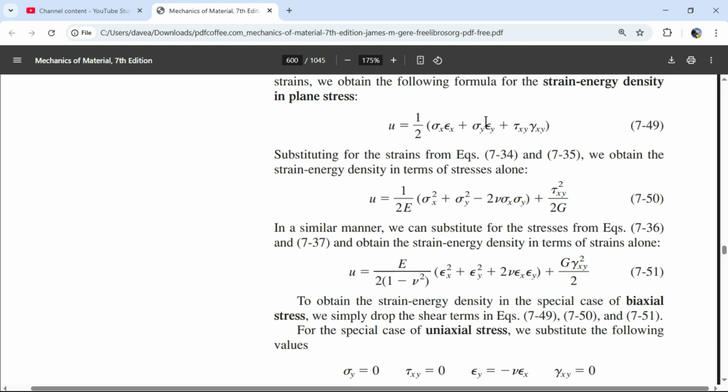And yeah, same thing here. When we substitute this in, we're for sure going to have, and just even think about that, this strain in the y is associated with the stress in the y. So we're going to have a sigma y plus a sigma x times Poisson's ratio. You know what I mean? And it's going to be a minus, because that's going to make it go the other direction.